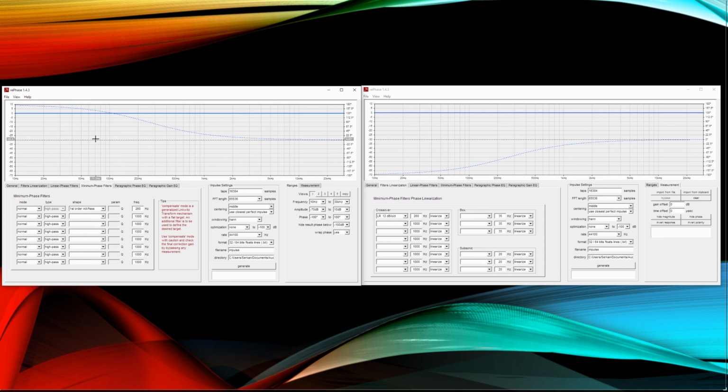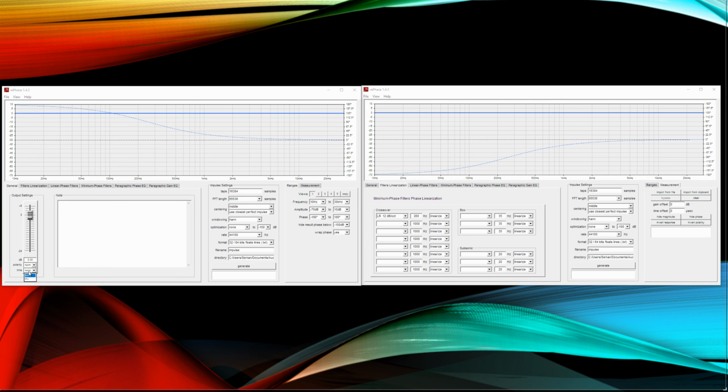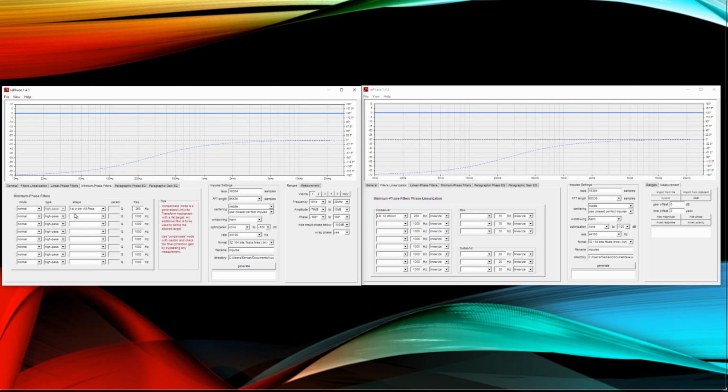To counteract this phase shift that this is causing at 260, there is this twist, and there is like a 1 pi movement throughout the frequency band from pi to 0. This needs to be time reversed so that it compensates for this phase shift. And time reversing you can do here, time inverted. And when you do that, as you see, it's exactly the same filter as the phase linearization tool of rePhase. So this is actually nothing more than a first order all pass time reversed.